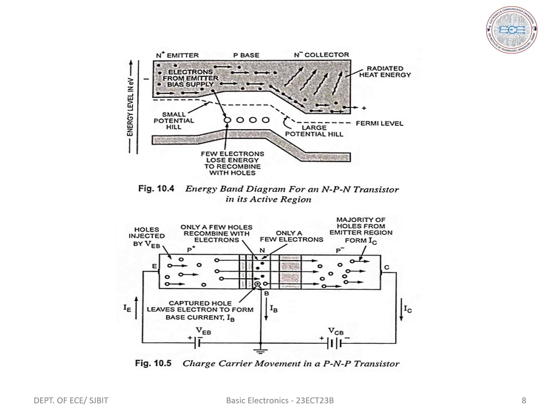The remaining large number of electrons will pass through the depletion region of the CB junction and through the collector region to the positive end of the external supply voltage VCC. Therefore, the collector current IC is much larger than the base current IB.